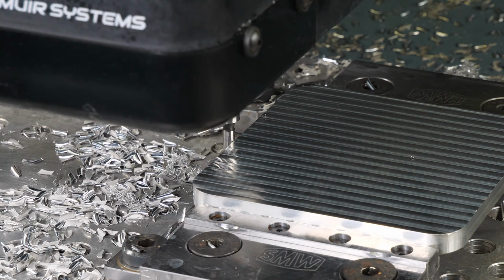And you can back it up a little bit, get some more practice in there, see it start to wobble again. I'm going to bring it back until I see that wobble disappear. It's gone. And I'll step it over until I see it stop. So now I'm going to back it off, maybe 2 thou. I'm going to raise it up.